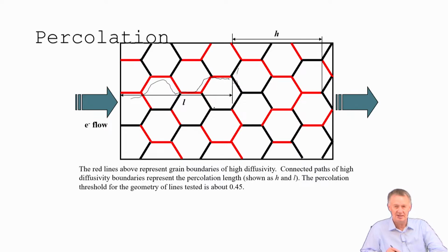So there's a lot of other ways to describe boundaries, and we do a lot of these things, but I'm not going to go back to those. We're just going to focus on our distribution functions for now. But just recognize that you don't have all the information just because you have these nice functions that have all your crystallographic parameters. Right? There's a lot of other things we can do mathematically to describe what's going on in your structure. This percolation is a really nice way to look at stress corrosion cracking. If anybody works on stress corrosion, it's almost always intergranular, and it's almost always your susceptible boundaries that are popping open.